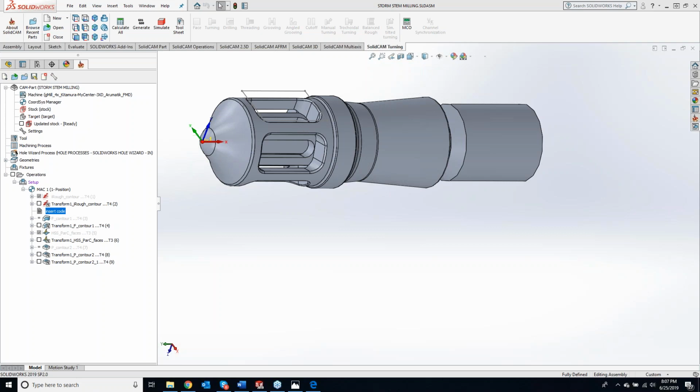Perfect. And a lot of guys will do this as well. At my old work, on some of our machines, we didn't have a probe. So I would always zero off with an edge finder in my y-axis, but I would also write a short little program to call up tool number 1, which is a spot drill, and it would come down right next to the part. Then I could slide my part up to it to be my x-axis 0 pin, tighten my vise down, hit cycle start again, and the spot drill would go up. I would just use my spot drill as kind of like a dowel. So a lot of different options there for you guys.